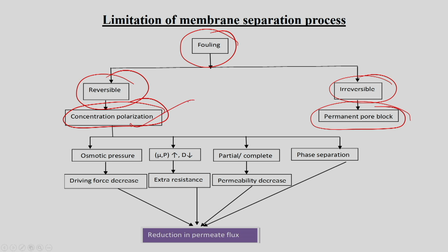For this concentration polarization, we can say osmotic pressure is developed, then viscosity will be increasing, then diffusivity will be decreasing, then partial or complete pore blocking will take place, then phase separation also will take place.